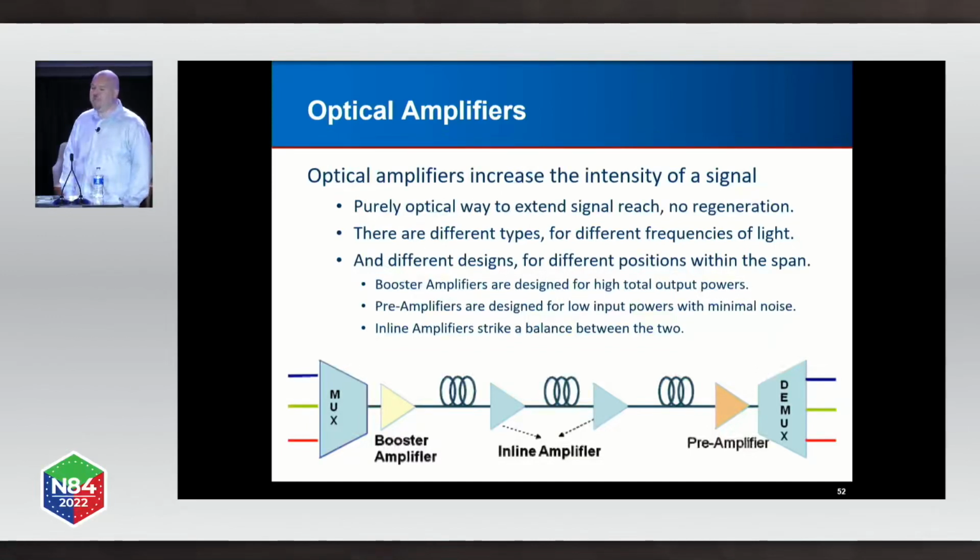So there's different kinds of amplifiers that you'll hear talked about as boosters, preamps, and inlines, and these aren't really strict roles. There's not actually a difference, like, this is a different technology for a booster. It's a slight variant in how they're built, and so you'll have an EDFA or an amplifier that's better in this role or better in this role, but it's ultimately up to you, as the network that you're building, what you do with it and why.